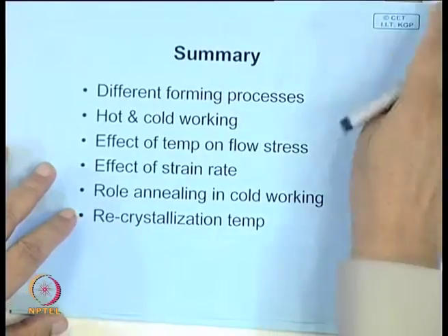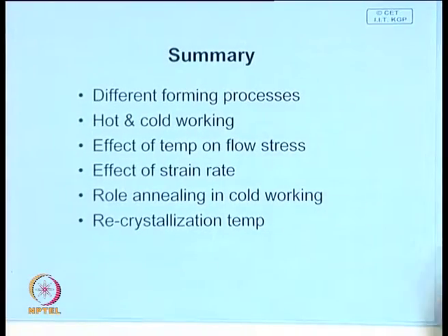So with this we finish today's lecture. What we talked about is deformation processing. Now, deformation processing is necessary, first, primarily to remove the cast and dendritic structure in the material. Next, we also saw how deformation processing can be given. There are several types of processes. They can be classified based on the way the stress is applied.